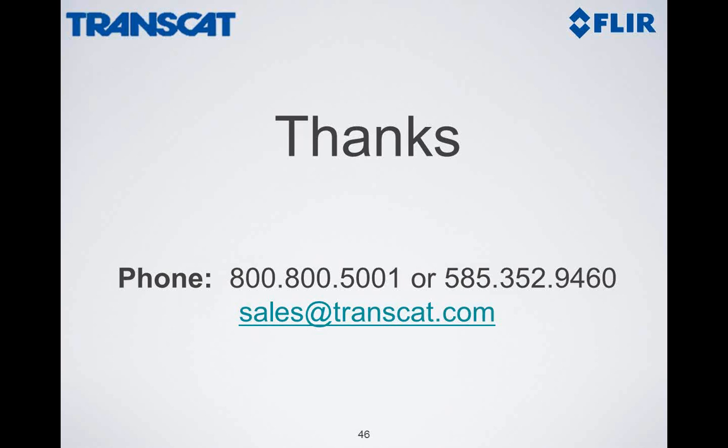Another way to look at it is sensitivity. Sensitivity is the ability for the T400 to resolve subtle temperature differences. I believe the T400 had a sensitivity of 0.07 degrees C. So there are other cameras out on the marketplace that go far below that.